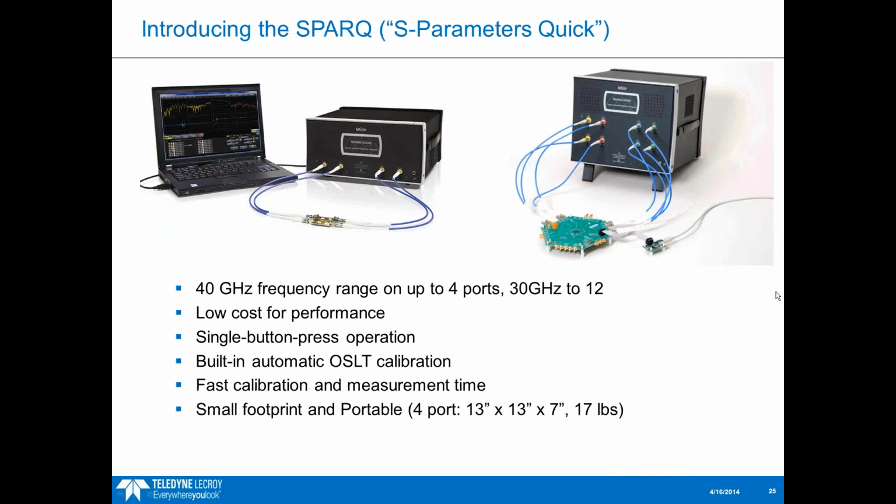So that covers the 4 different S parameter patterns I wanted to cover today, as well as the relationship between insertion loss and return loss. So hopefully that should help you get some insights out of your S parameters. I know looking at S parameters, if you don't have a lot of experience with them, can not be the most intuitive experience. So it's good to have some rules of thumb and some patterns to look for in them that can help you gain some insights into your interconnect and connect real-world features in the interconnect with things that you see in the S parameters themselves.